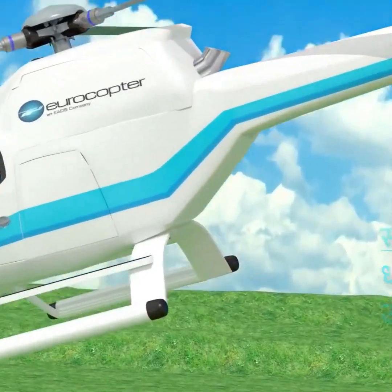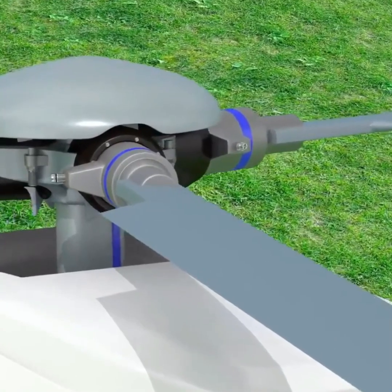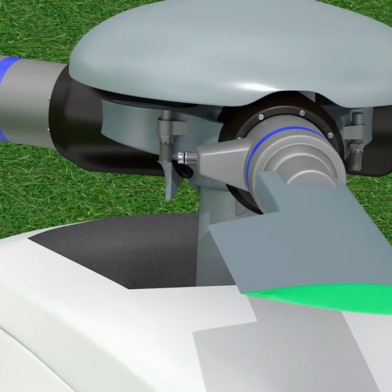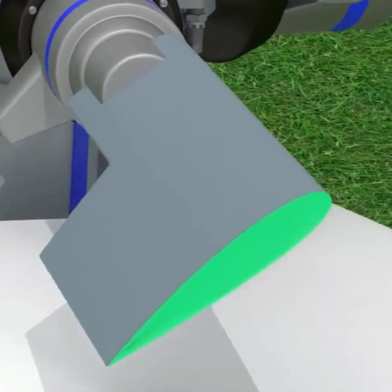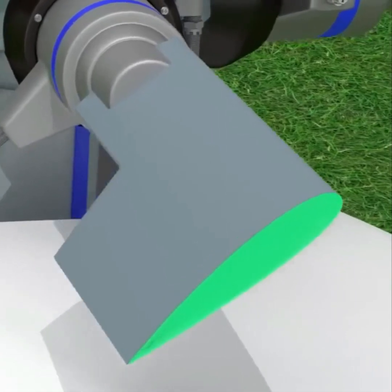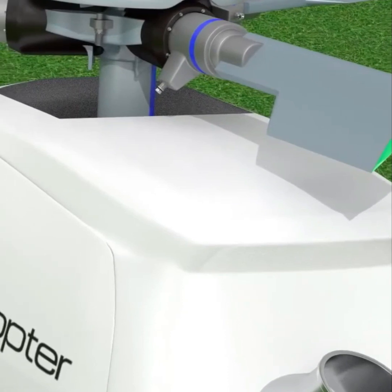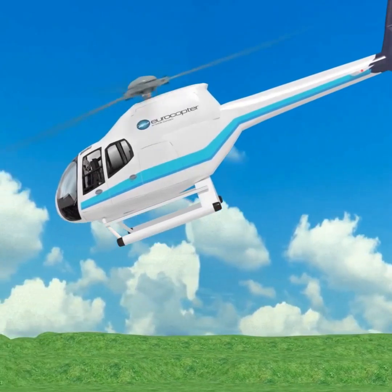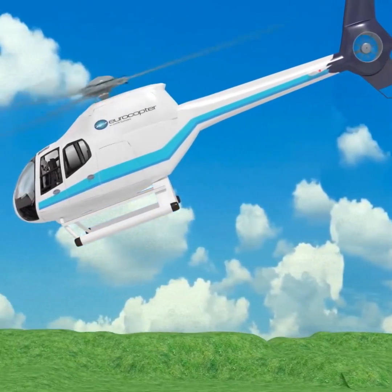To understand the science behind helicopter rotation, we need to delve deeper into the airfoil principle. The thrust generated by the airfoil, similar to an aircraft wing, changes with the angle of attack. Generally, a greater angle of attack results in more thrust. Now, imagine what would happen if one blade were at one angle of attack and another blade at a different angle of attack. In this scenario, the thrust on the blades would differ, creating torque that rotates the helicopter.